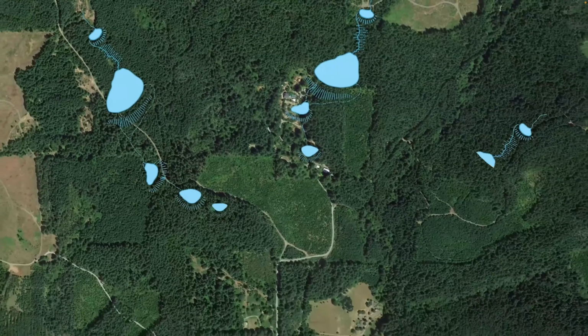You can also have an overflow swale that's separate from your spillway to do a similar function if you have the type of soil and the surplus water to do that. Generally speaking, I think it's very important to consider the idea of moving water from valley out to the ridge and back to the valley before just moving it from one valley to another.